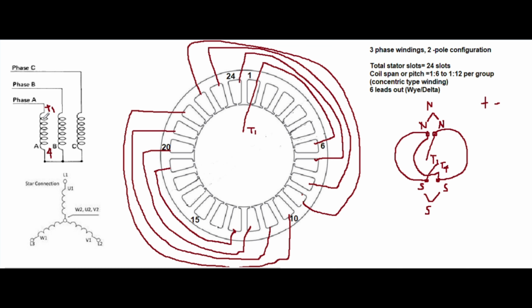Okay. There will be 8 coils in this phase. So in reality, one group of coils is formed using this one. Let's say we have one coil formed for 1 to 6, let's say 100 turns, one form. Then the next form, let's say another 100 turns, next another one, until you have the fourth one. So this is 1 to 6, 1 to 8, 1 to 10, then 1 to 12.